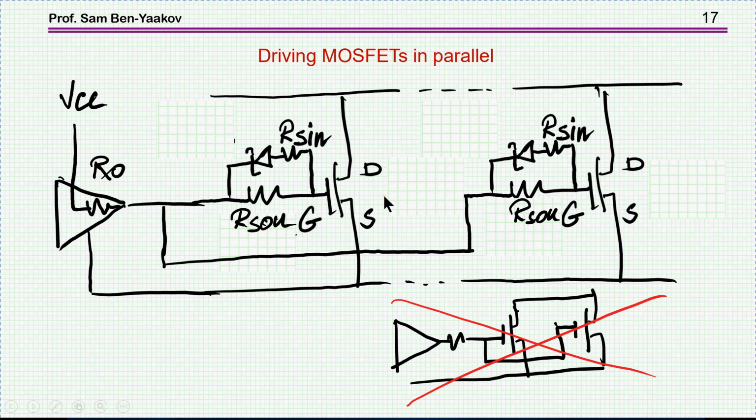So therefore, you would like to put these resistors such that the voltage drop of the resistor is appreciably larger than the deviation that you would expect, such that if this is a certain voltage here, a small deviation here relative to the voltage here will not cause a large difference in the current between, say, this resistor and this resistor. We'll see this in a minute.